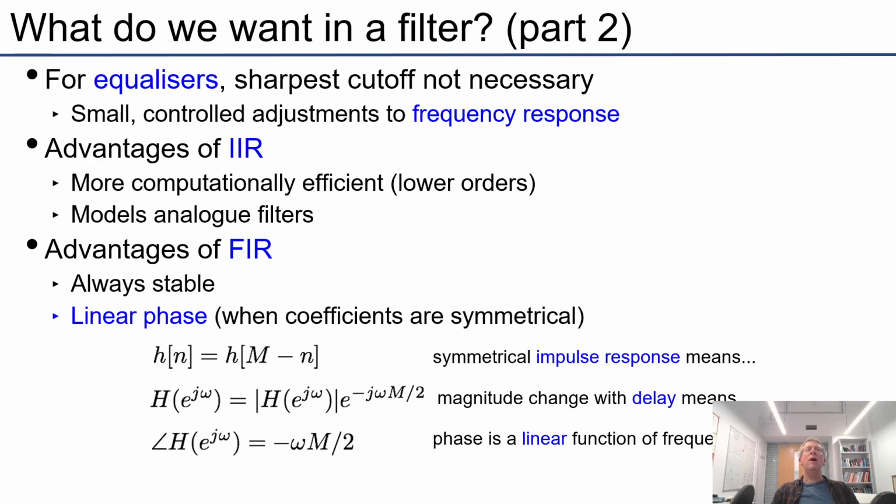So when shaping the frequency spectrum and not concerned about an artifact like aliasing, then one generally wants a smooth rather than a sharp filter. With both cases, of course, it can depend, but usually when people are doing things like equalization, a lower order smooth filter is perfectly fine.